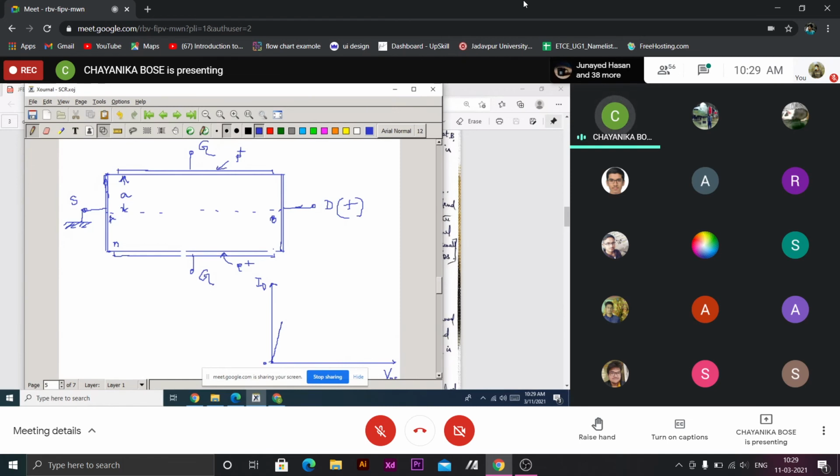So with respect to point A, as we move towards the right, toward the drain side, the channel experiences this higher positive potential, and at the point B, it is maximum. The value VD, say VD is 5 volt. So at this point, the N channel gets plus 5 volt, and there is a gradient from 0 to 5 volt distributed across the length of the channel.